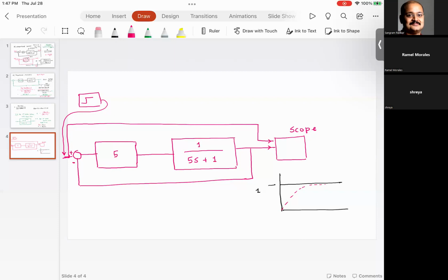So how does your output look? So this is the simple proportional control. And what I want you to do is change this proportional control from 1, let's make it very small, say 0.5, to 5. So run this iteration and see what effect it has on your system response. Please observe what it does to your system response.